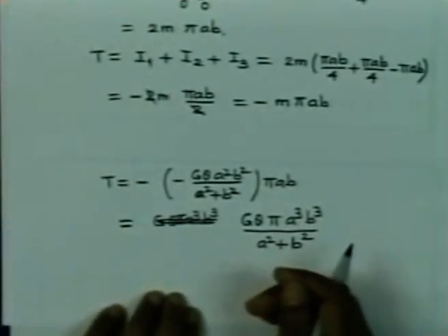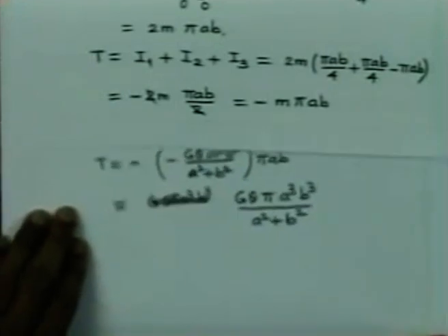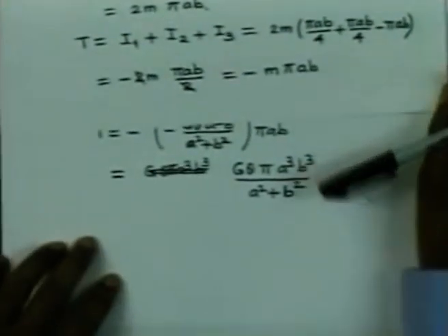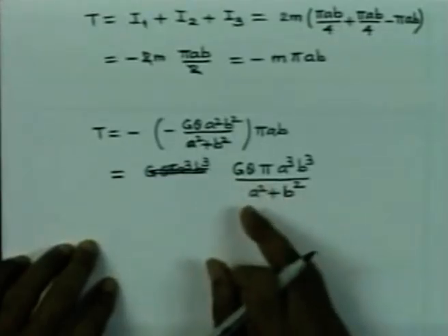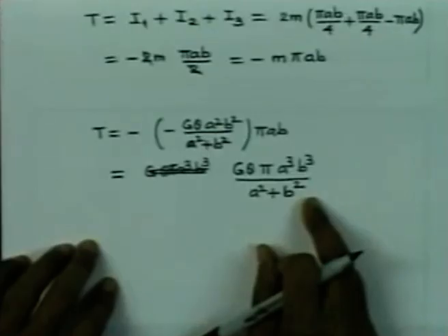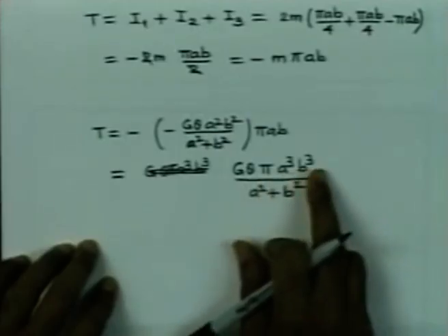So, this is the relationship between the angle of twist per unit length and the cross sectional dimension with the applied torque. You can see the units are in perfect match. You have G given in Newton per meter square and dimensions will be in meter. So, we are going to get Newton per meter square into meter square, and therefore, it will give us Newton meter. So, torque will be Newton meter.